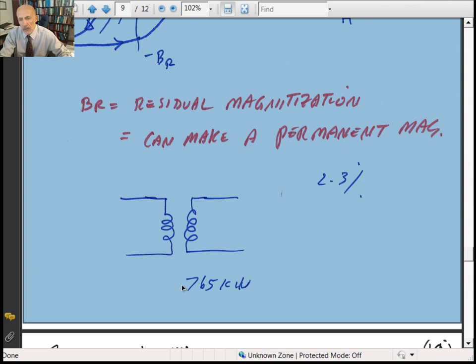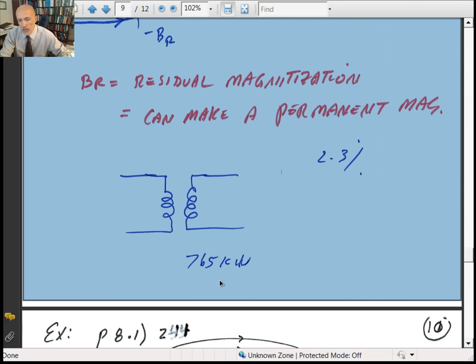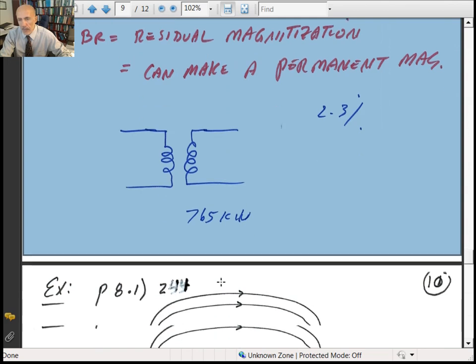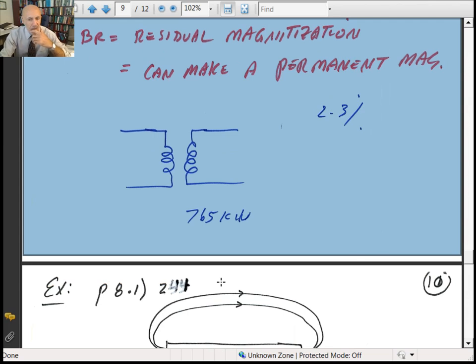Another loss associated with transformers is called eddy current, which is the heat loss in a transformer. To reduce that, they put in a sheet of insulated laminations, which puts a large resistance on the path, so it minimizes the eddy current. So you have a very small current going inside the ferromagnetic iron core to reduce that heat loss. But we're going to talk about that more when we discuss inductances.